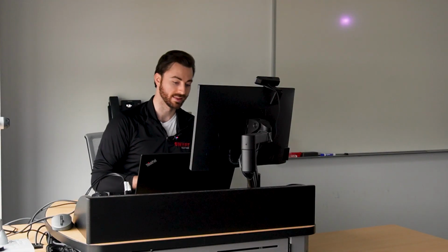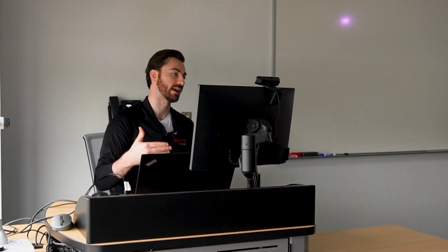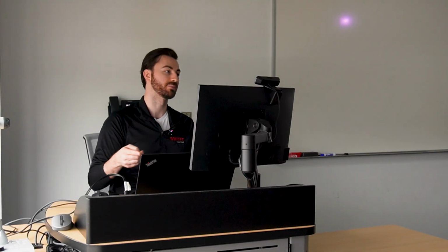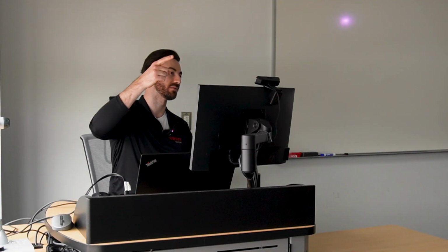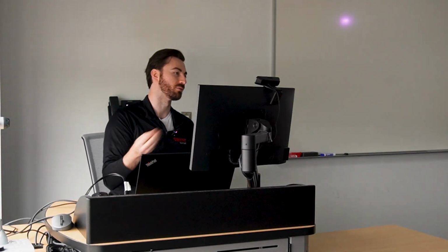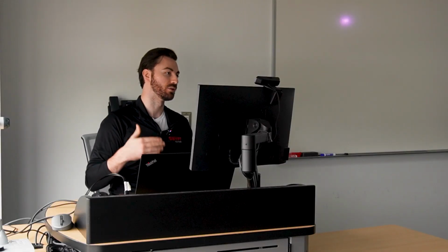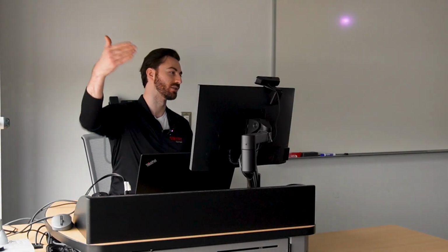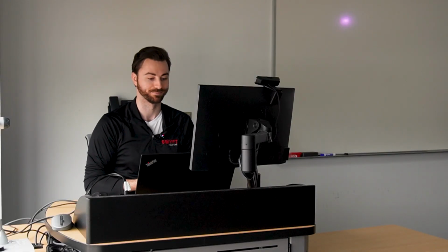Just a couple of notes on this side of things. If you do create a revision of a part and you would like to have that reference updated in the assembly, that has to be carried out in SOLIDWORKS. So in this example, I created the revision of that crank, but it automatically replaced it in the assembly, and then I had to save the assembly. That's just because I had SOLIDWORKS open and it had the reference and only one could be cached. If I created the new revision of the crank on the web portal, the old assembly, you'd have to open up that assembly and know that you have to increase the revision of it to pull the updated revision of that crank into it.